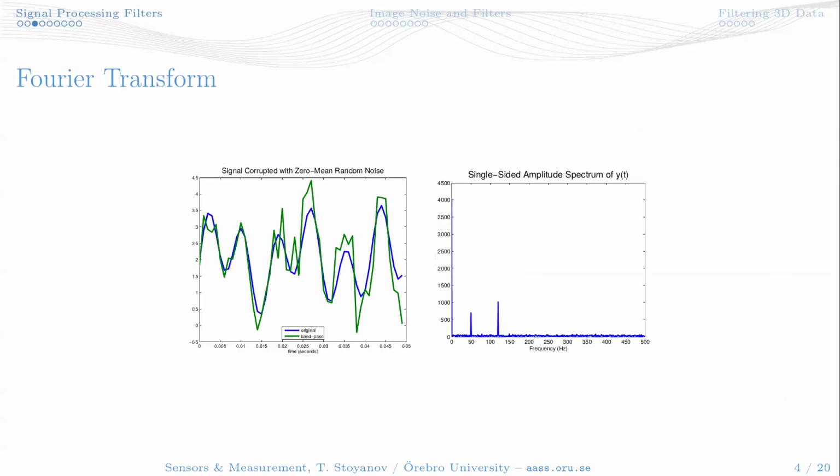So typically, if we take the original signal here that we looked at, and we take the amplitude of the spectrum, we'll notice that, okay, there are a couple of components here. So this is the steady state, right? So that's how far up from the zero the mean of the signal is, right? That's the frequency component of zero. But then you'll notice there's a strong frequency component here at around 50, and another one at 120, something like this. And the rest is actually noise, right?